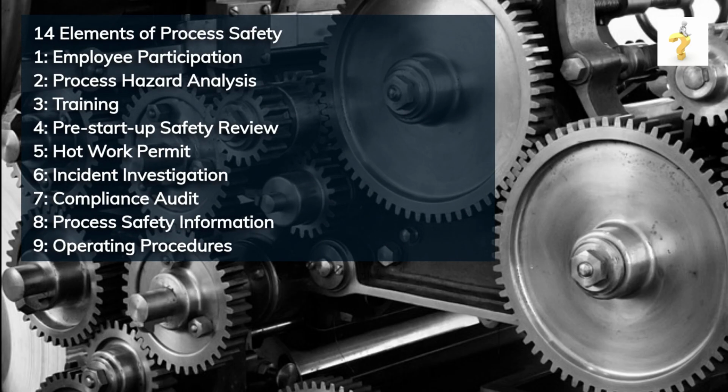The ninth element of PSM is operating procedures. Clear and well-documented operating procedures provide step-by-step instructions for safely conducting processes. They outline the sequence of operations, safety precautions, required equipment, and emergency response procedures.